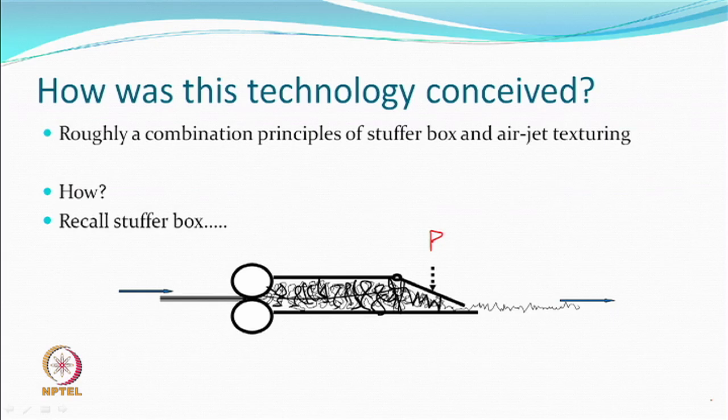So, there is a plug of bent yarn which is made within the box, and the textured yarn is brought out from the other side. So, in a way you have a pliable yarn which is hitting a wall and so bending, a simple process, and then of course you cool down so that this texture remains.